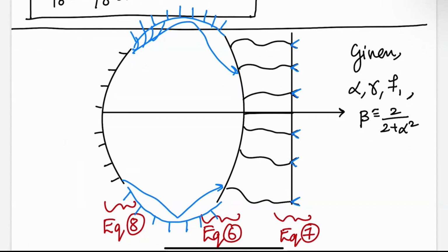But yes, that essentially completes the Rotman lens. What we'll do is set a polynomial that joins this end to this end like this, based on some points. Ideally you want to make this kind of sharp. You don't want it to be flat like this, otherwise you'll get a very strong reflection. If it's something like that, maybe you get some reflection back this way and not much that goes into those ports. That's what we'll try to do.